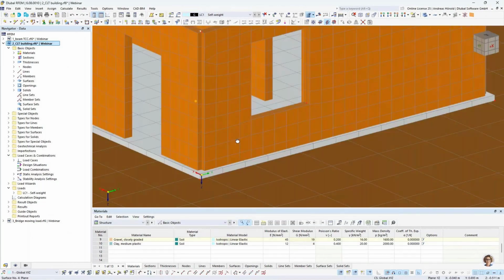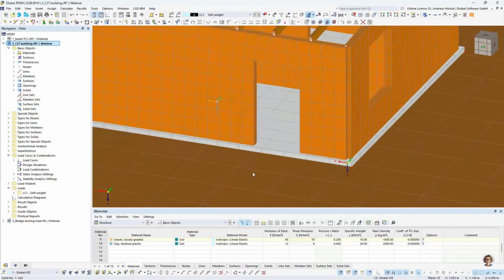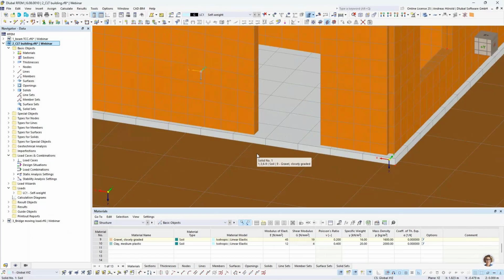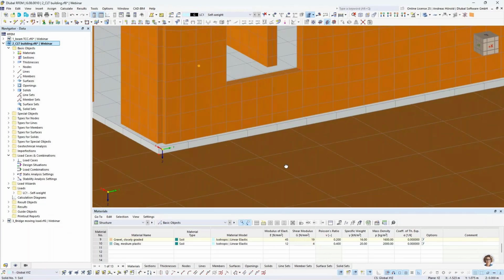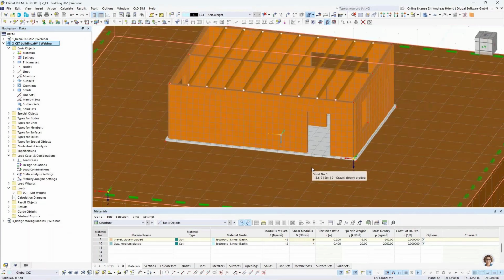So it's much better now. And as you can see, the finite elements do not have to touch at a common node. And the finite elements of integrated objects are connected to the integrating one. Quite a good option for FE calculations with different FE mesh settings of the elements.